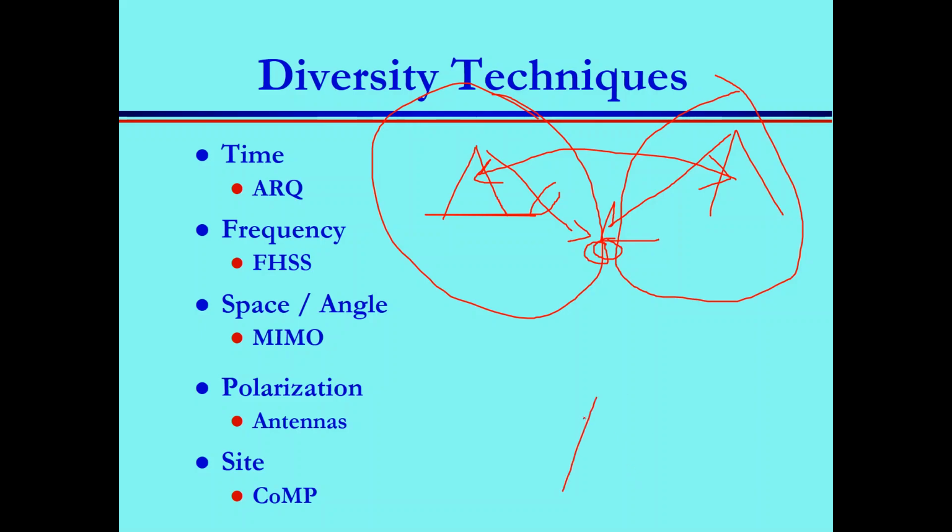Of course, you can have another base station collaborating with these base stations, and share the data of the user and send it to him. So he gets 3, 2, 5 links. And this ensures that the receiver who is located in a very bad situation and not able to receive his data correctly from a single base station can now jointly receive all these signals together and amplify his signal to noise ratio, and therefore reduce the outage.